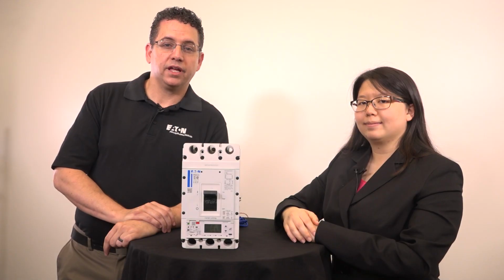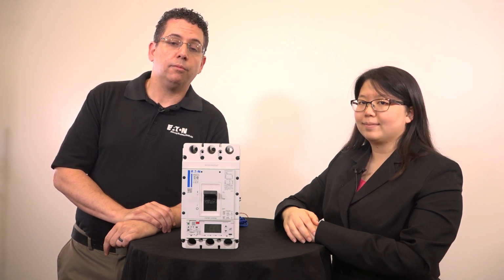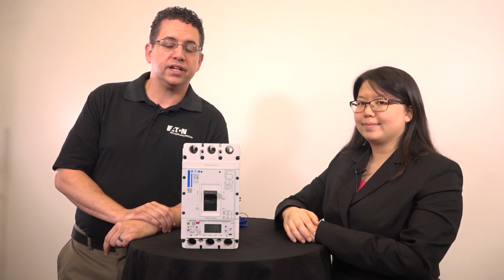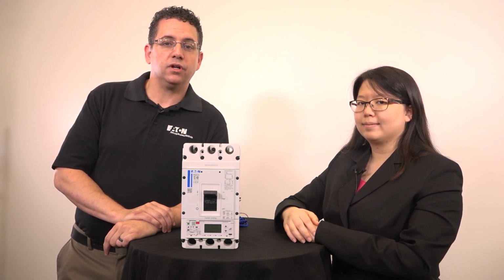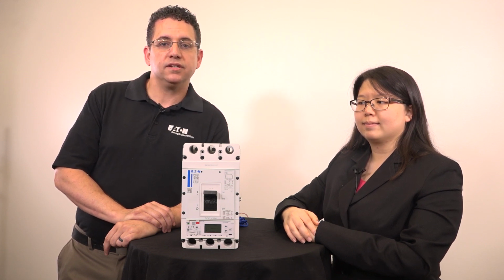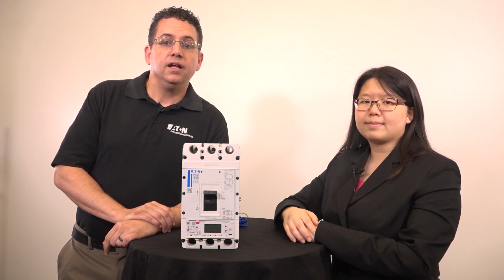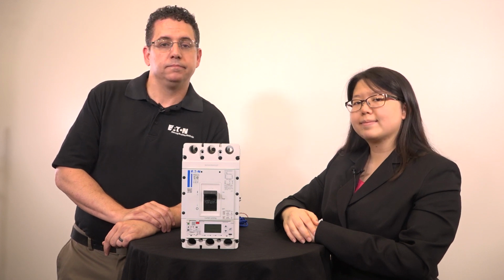Electronic circuit breakers can be complicated. Electronic circuit breakers can do much more than their thermomagnetic predecessors. Like any great team, all the parts need to work together in unison. Normally, when a circuit breaker is in operation, we have current passing through the current sensor. This sensor interfaces with our PXR trip unit and all the circuitry there. Think of it as the PXR trip unit being the brains of the breaker.